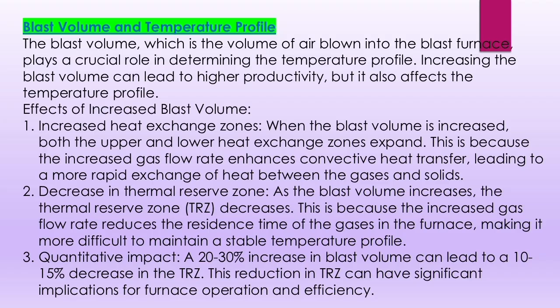When the blast volume is increased, both the upper and lower heat exchange zones expand. This is because the increased gas flow rate enhances convective heat transfer, leading to a more rapid exchange of heat between the gases and solids. 2. Decrease in thermal reserve zone.